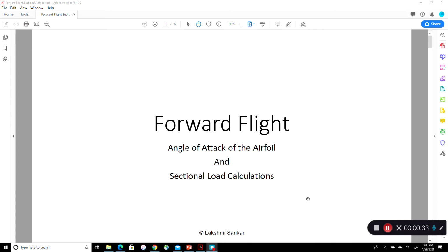And once you have chosen a coordinate system, we know in that coordinate system the blade is going to be flapping up and down. If it is not a tip path plane coordinate system, but in the tip path plane coordinate system, it will only have a steady coning angle. There is no flapping up or down. Likewise, because of the pilot's control actions, the blade is going to be pitching up and down as it goes around the azimuth. Again, if it is a no feathering plane, you will only see a collective pitch. That means a time invariant pitch that is seen by all the blades all around the azimuth. So we have some information now available.